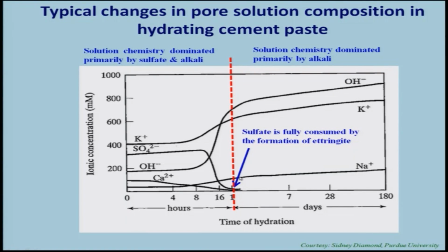In the third one, what you see is that the sodium that is present as minor compounds slowly increases because they do not actively participate in the hydration process and they are present in the pore solution, and at an age of say 180 days the concentration of sodium is the highest compared to that at 0 days. Likewise, if you take potassium, at the initial level it is generally high, and with time it increases, and finally at about 180 days it is extremely high.